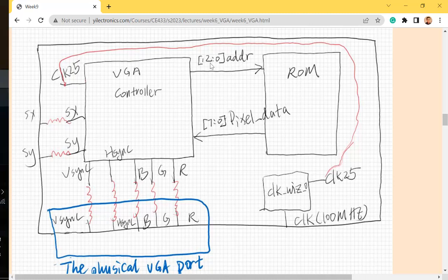Keep in mind, do I have a clock signal for the ROM? No. Whenever a 13-bit address is sent to it, it has a decoder, but you are not designing the decoder, because you just write it in Verilog. Whenever you receive this address, you just take that data out. It's very simple. It will synthesize a decoder inside, but you don't have to know it.